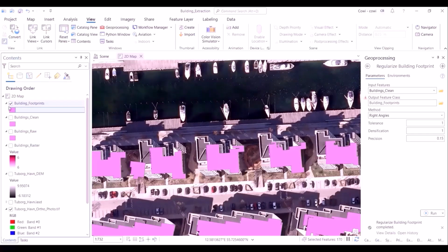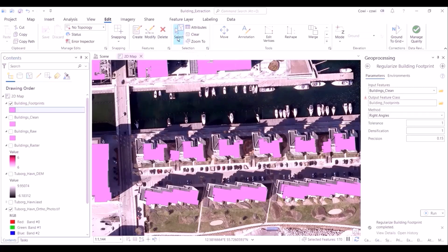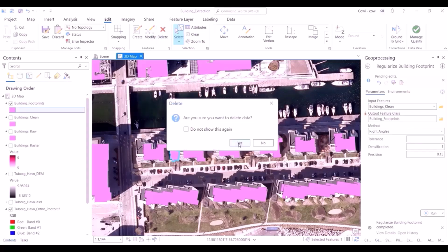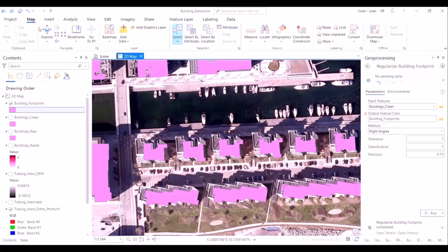Subsequently, you will see on the left of your screen a small object, for example, that has been incorrectly identified as a building. Now, this matches the building minimum area criteria, but it's still not a building. Then what can we do? We can select that particular object and remove it manually. So this is again another type of corrective measure which we can perform.